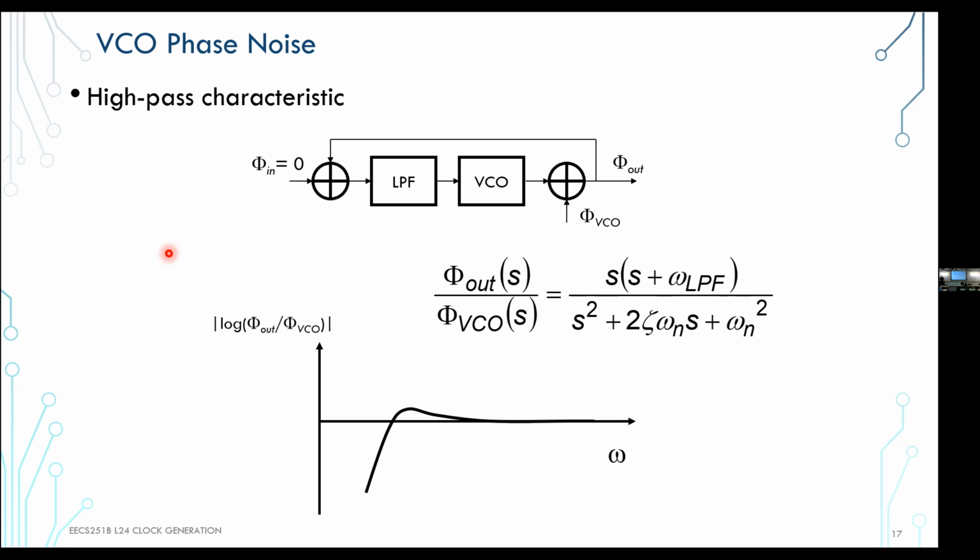And so if you're not careful, you create too wide a bandwidth of PLL to suppress the VCO noise. You're now admitting all that reference clock noise into the system. So you've got to be careful. Because remember, clock buffers have higher frequency noise, right? And it's going to be right about where you're peaking in your loop bandwidth, so it could be pretty nasty.